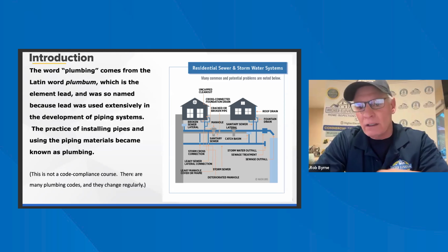Clothes dryers. What we look for when we're doing this is to see if there's a standpipe which is connected to the waste stack. A lot of times when we do inspections, the hose is in a sink. It's not really the right way to do it because the standpipe is designed more to handle this flow and volume, with less chance of it getting clogged. The drain is smaller. It can get clogged. You can wind up with the sink overflowing if you're not down there.